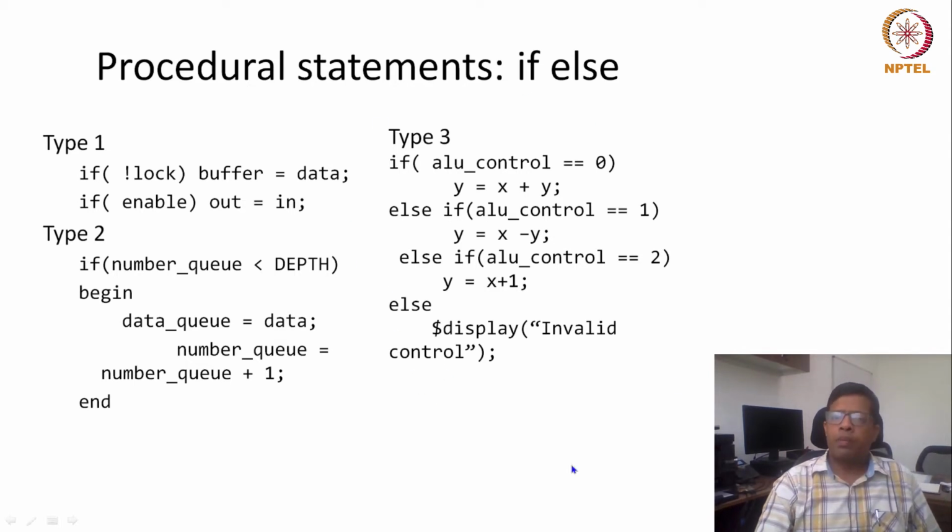Another comment here is that this if else ladder, or if else case, is also very similar to priority. If you're designing something like a priority encoder, this if is going to have the highest priority.